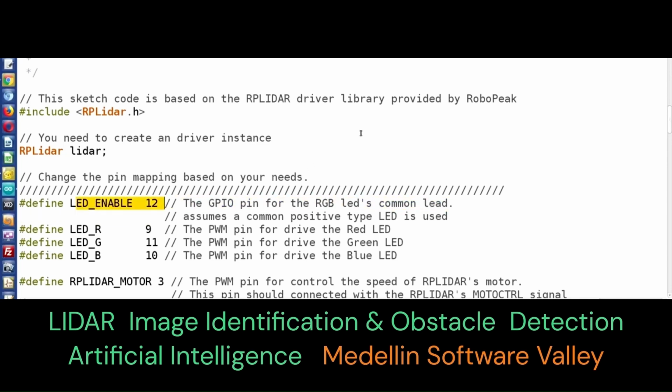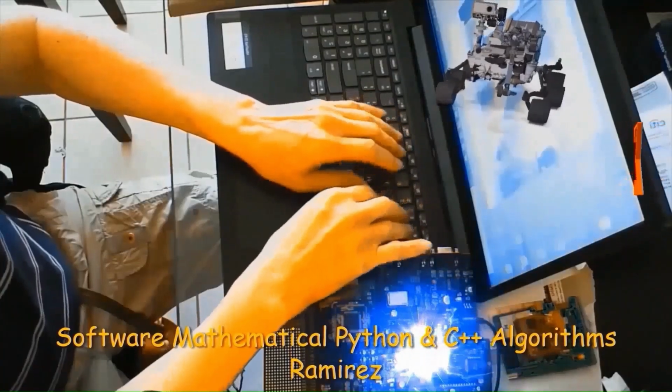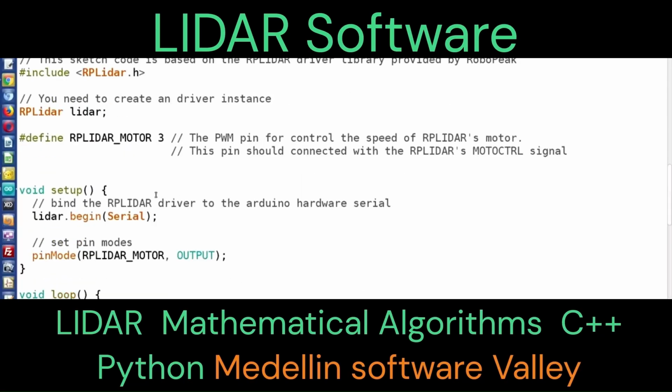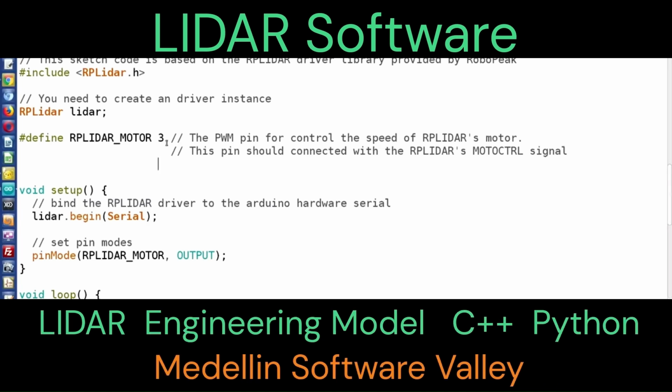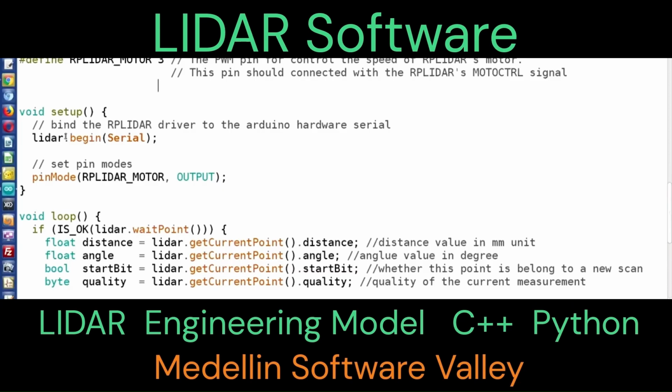In the receiver, the reflected light signal is detected by the photodiode, which produces a current proportional to the return signal strength. The current signal is converted to a voltage by a transimpedance amplifier, which is typically implemented as a discrete component outside of the system-on-chip architecture.